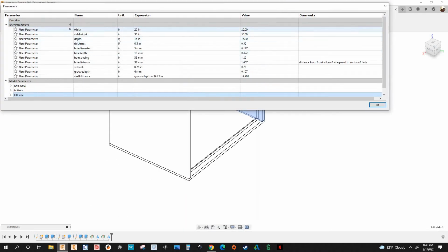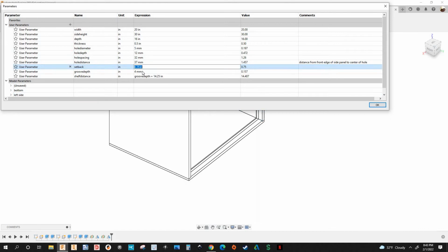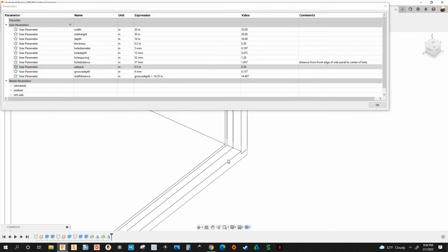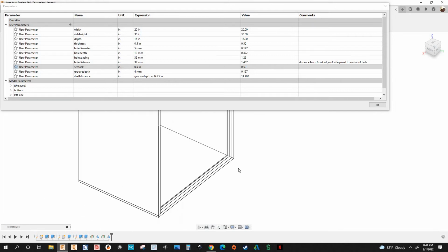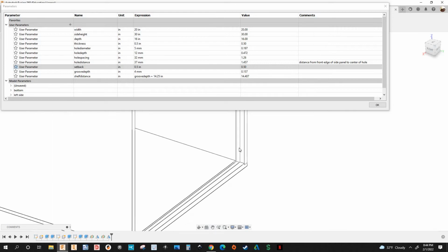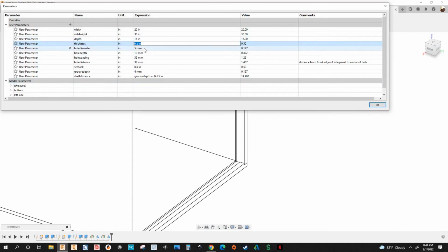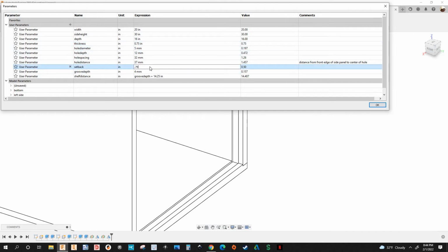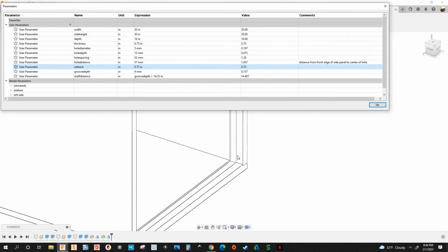Let's go back to change parameters. Let's go to that setback parameter. I'm gonna type 0.5. Boom. See that? Now it's half inch. Okay. So let's change that thickness back to 0.75 inches. And that setback to 0.75. Let's say you're gonna have a plywood blocking here. Okay. And it happens to be 0.71. Right, it's a little less than 3/4. 0.71. Hit enter. I'm gonna click OK.